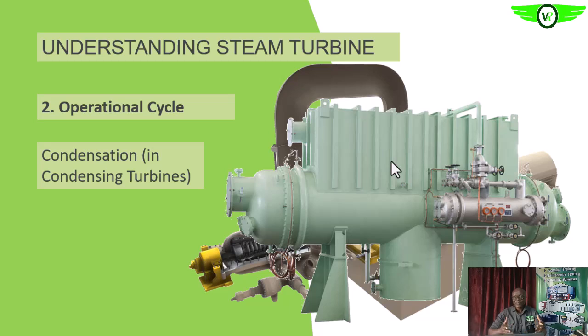Then as that is happening, you see that sharp reduction in pressure as you condense from steam to water, that reduces the volume, okay. That reduction in volume causes a change in pressure, causes reduction in pressure. So that reduction in pressure is what will help to create that vacuum. Are you getting it? That will now pull more steam into the condenser, this unit.